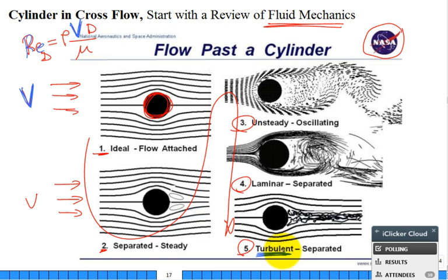Anyway. So what are they showing you by these lines? Let me see. This line that goes like this. What is that line? It's as if I dropped a little pack of colored dye fluid and I traced it. It would just go like that. That's the flow line, the streamline, streak line. Now, when it's steady state, and these are steady state, then all those terms boil down to the same thing. It's when it's transient that in fluid mechanics there's a difference between a streak line and a streamline. What does it show about the fluid packet that's just a little above the center line? What does it do when it gets close? It just goes around, and that's it.